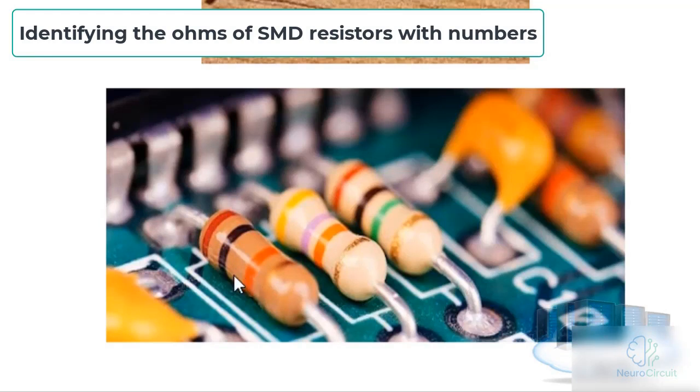Even if you test this resistor with a multimeter and it shows the correct resistance at that moment, it's still better to replace it. So my advice is, if you see a resistor whose color has changed like this, definitely replace it, even if it shows the exact resistance at that moment, because these resistors will have problems during operation. But when the device is off, it might show the correct resistance, and these are experiences we've had in repairs.